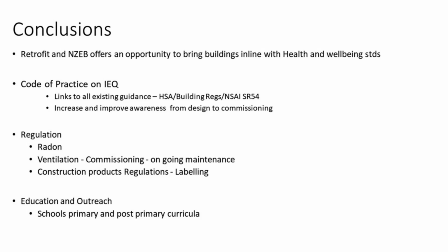Maybe we need a code of practice on indoor environmental quality to support the retrofit process. There's a lot of good guidance out there. We've got guidance relevant to the Health and Safety Authority, we have our building regs, advice from the Department, NSAI guidance, but it's all very fragmented. We could pull that all together and help increase awareness amongst everyone who works from design to commissioning with regard to indoor air. In terms of regulation, we're not going to be able to measure, monitor and regulate indoor air for all the different pollutants we can detect indoors. But one we should be considering is radon. Can we make radon monitoring mandatory as part of retrofit? I think it's important. There's an opportunity there.